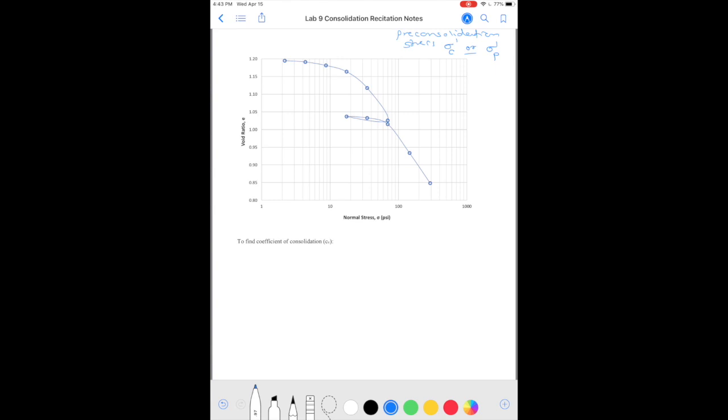So imagine that if we have a soil layer that's settled under its own weight, the pre-consolidation stress is going to be the overburden stress at that depth where the sample came from. But there could have been an iceberg sitting at that location thousands of years ago. In that case, it has seen higher stresses in the past than the current stresses.